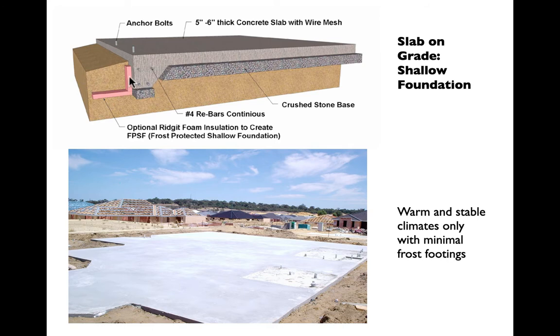We'll usually design the foundations of a slab on grade with a little bit of a perimeter beam to handle the loads of walls coming down onto them, also just to give some rigidity to the edge of the slab. We'll excavate and remediate, so we'll take off 5 or 6 inches of organic soil, and usually we'll put some kind of gravel base. And the gravel, first of all, is going to bear very well, so it's going to transmit loads equally to the soil below it.